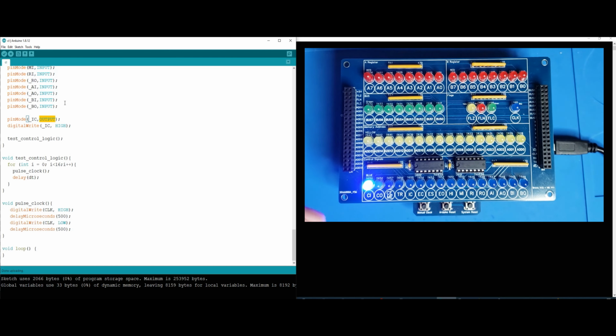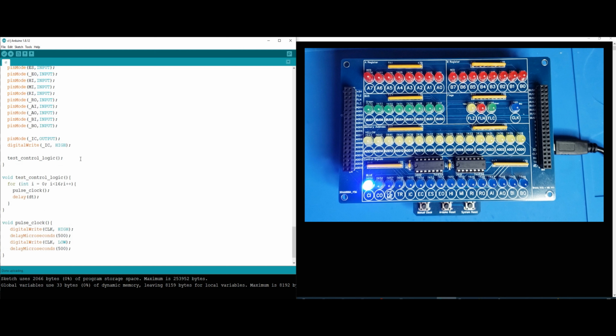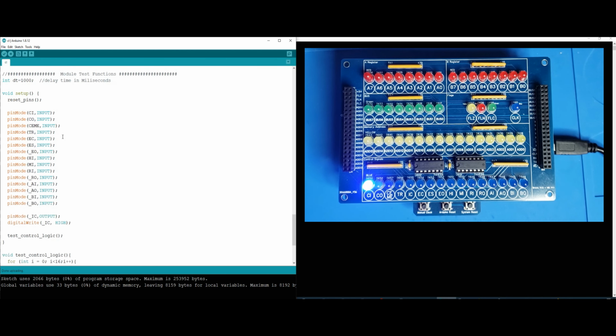However, the rest of the signals are outputting fine from our control ROM. So this is a very, very simple test, just to check that our instruction register is able to address our flash memory, and we see all the control signals are outputting fine. Obviously, you could be more creative and come up with a more comprehensive test case here, and you could attach your memory module or program counter and test everything together.